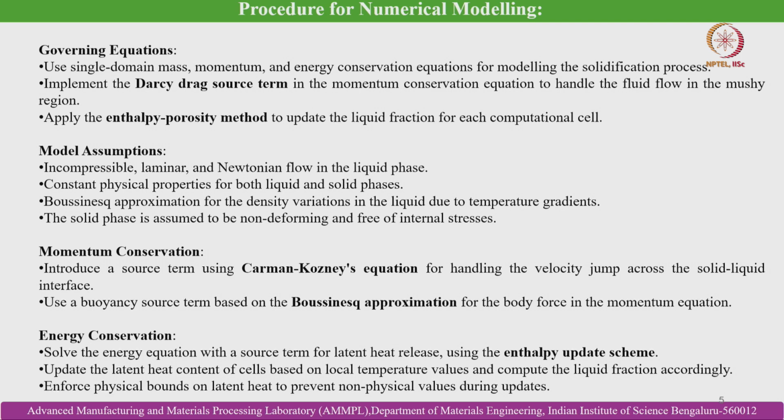And now the procedure for numerical modeling of the solidification process. So governing equations: we use single domain mass, momentum and energy conservation equations for modeling the solidification process, and we can implement the Darcy drag source term in the momentum conservation equation to handle the fluid flow in the mushy region, whereas the enthalpy porosity technique can be applied to update the liquid fraction for each computational cell when there is an impending phase change happening.